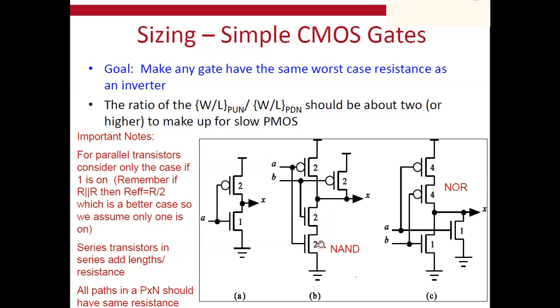That means that the overall is W over L. This is simply how you manage your transistor, because now you have a double length. So it's like you are making half plus half. So just see this number as 1 over 2 to make it very easy. So I need to make this equivalent to 1. Okay, great. This is 1 over 2 plus 1 over 2, and put these two here as your sizing parameter, and here 2 and 2.